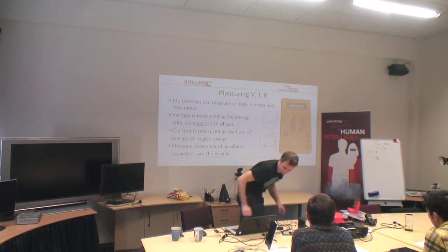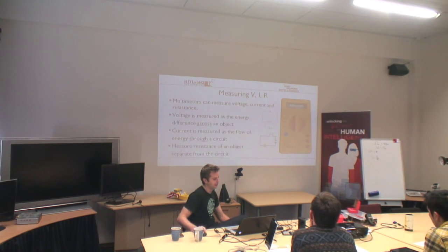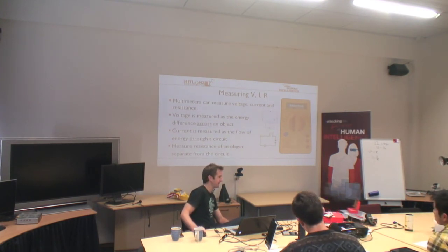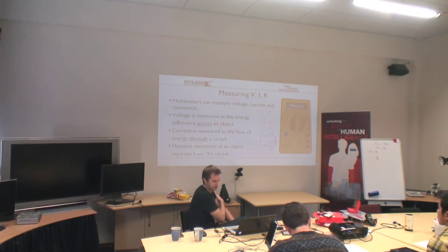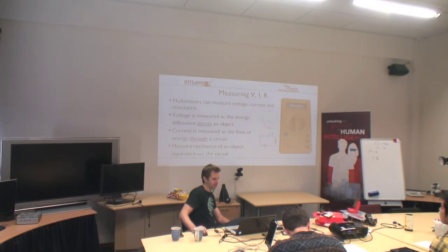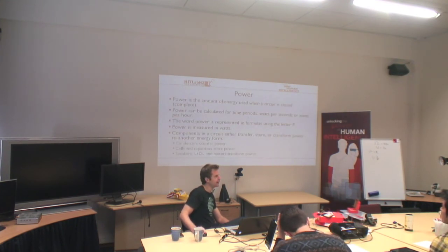So yeah, burn this into your memory, because we only have one multimeter that I can find, and if you're blowing the fuse every 5 minutes, you're going to upset a lot of people. So yeah, voltage across, current through, measure resistance separate. We've got a few more minutes.